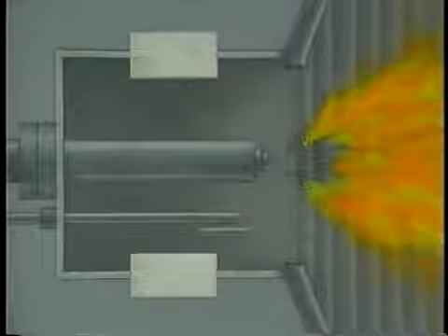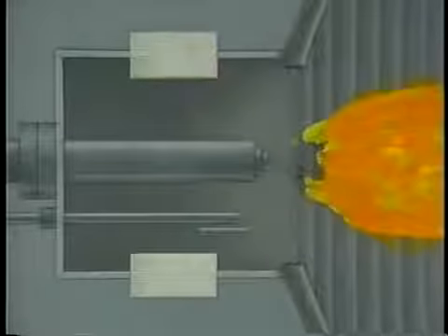If you have established a proper boiler flame and airflow and fuel flow are properly matched, your burners will operate the way they're supposed to. However, if airflow, for example, is interrupted, one of the basic requirements for combustion is eliminated. This will cause the boiler flame to go out. Unless the fuel flow is immediately stopped and the boiler is purged, an abnormally high concentration of fuel may accumulate near the burner port.